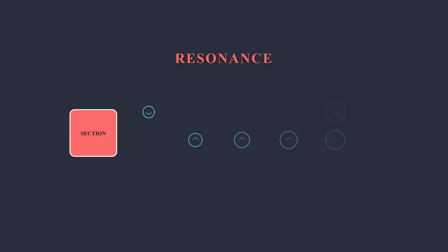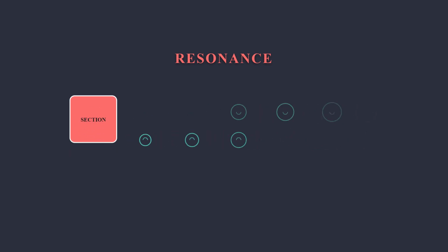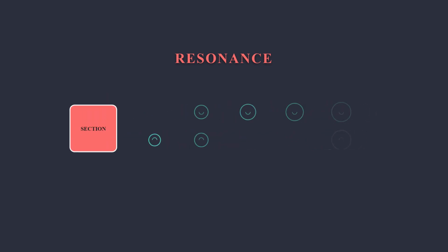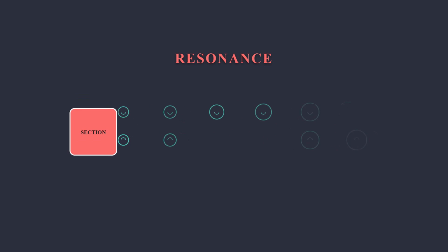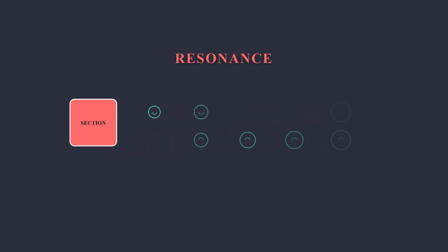incoming wind flow. When wind flows past a non-streamlined structure, alternating vortices detach from the sides, forming the Kármán vortex street. This periodic detachment process, known as vortex shedding, generates oscillating lift forces perpendicular to the wind direction. If the frequency of this vortex shedding aligns precisely with the structure's natural frequency, resonance occurs. Resonance leads to a rapid buildup of vibrational energy and potentially large amplitude oscillations threatening structural integrity.